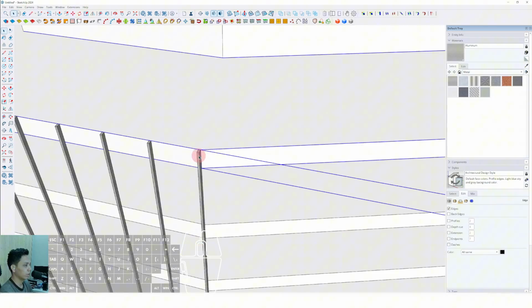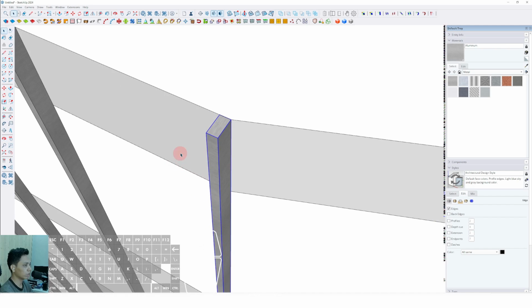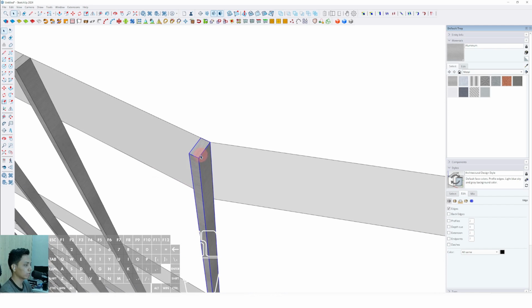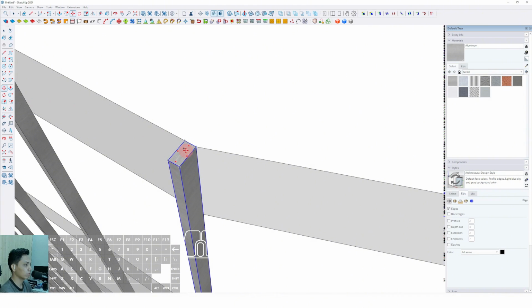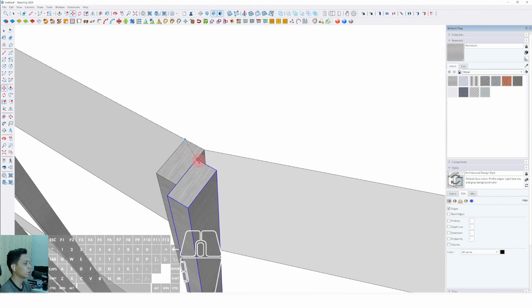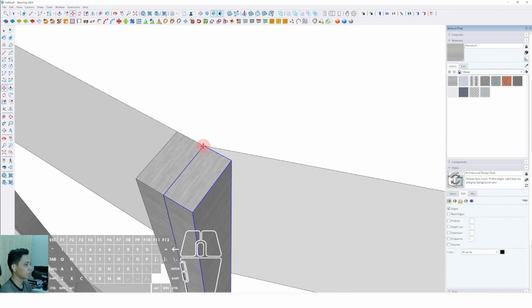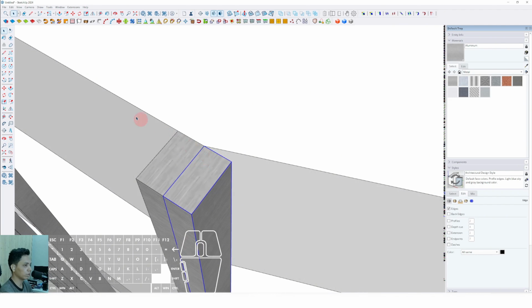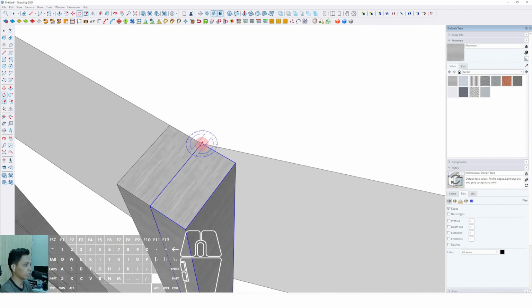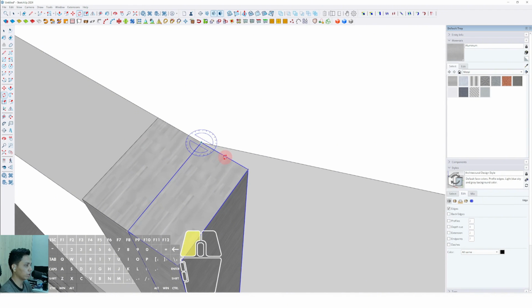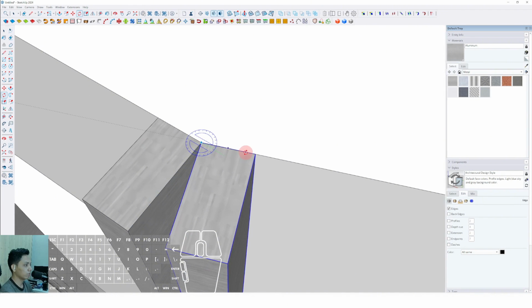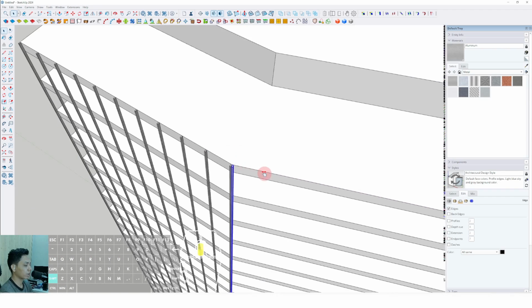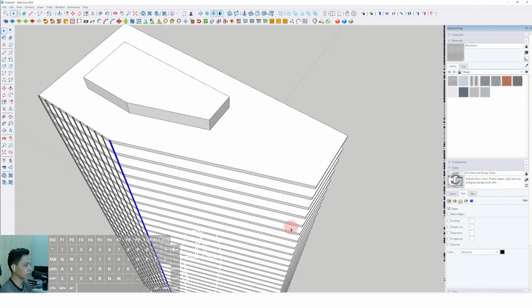Then we can continue to move and duplicate. Click this vertical frame, select move, press Ctrl, place to this corner position, click to this destination. Then we can adjust with the rotate tool from this corner. Click this midpoint and just adjust with the line orientation of this diagonal building side here.